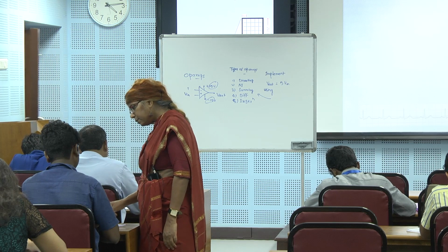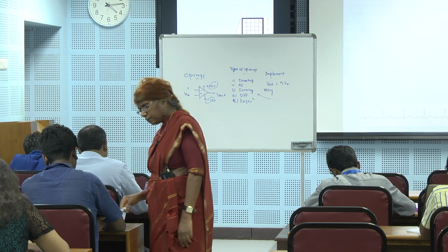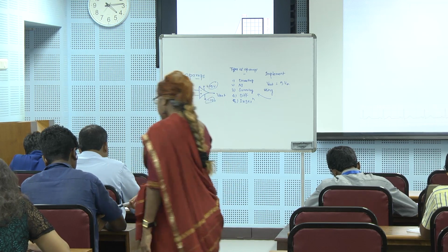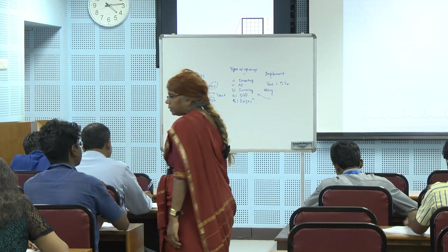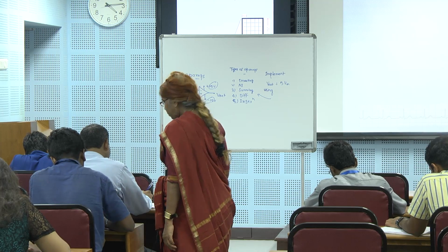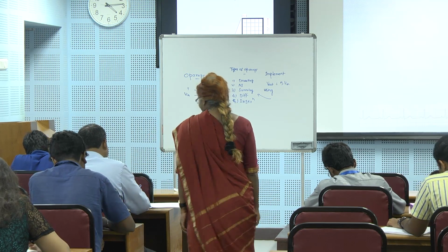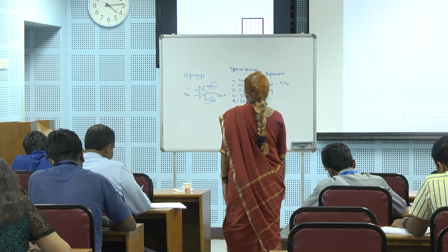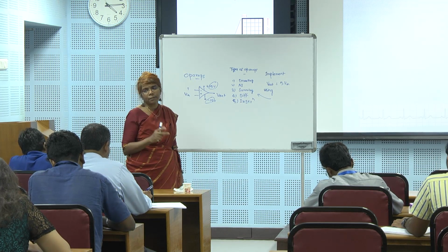It's not complete. No, it is. What's the V out? V out is negative, no. So put one more stage. I want 5 Vn, not negative 5 Vn. You cannot have negative, no. That is not correct. Your input is Vn, not negative Vn. So when you do the first one, you need to have 2 stages.